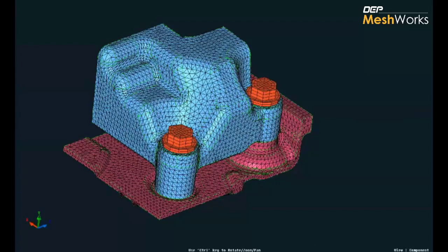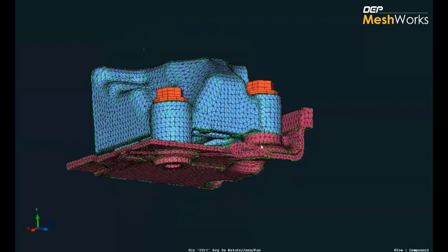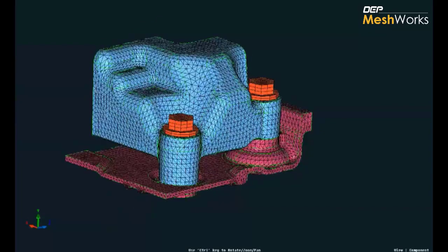So now we can see how we can quickly generate a Nastran model out of this particular scenario. So we can directly jump into the integrated modeler, and here we have the 3 options of generating a Dyna or a Nastran or Abaqus. So I'm just going to generate a Nastran model. So we have 3 attribute files. What you're seeing here is 3 columns, and we have a meshing attribute file, a modeling attribute file, and a solver attribute file. The meshing attribute file is what defines the meshing conditions.